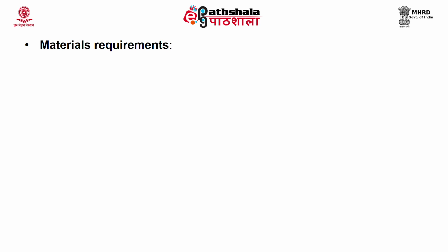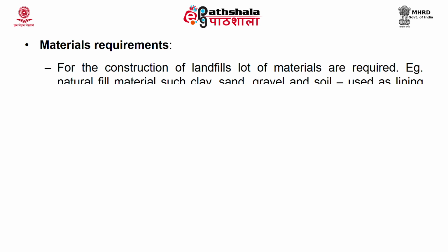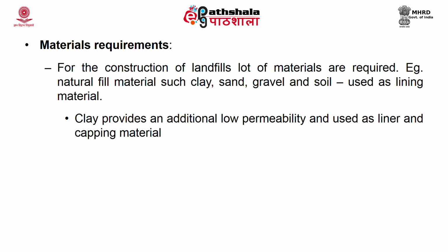The next consideration is material requirement. For the construction of a landfill, you require a huge amount of material, be it natural or synthetic material. Natural fill material includes clay, sand, gravel, and soil, which are usually used as lining material. Clay is the most popularly used lining material because of its low permeability.